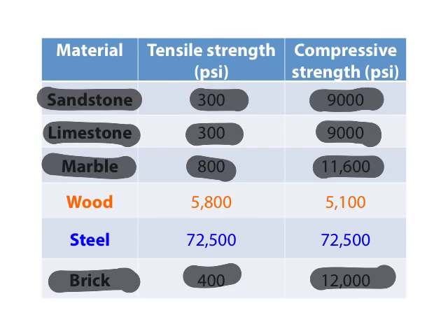So what that means is that stone is a great building material if you're using it in a situation in which it's undergoing compression. It's the perfect material for it in that sense. But you would never want to use stone when it is placed in a position where it's undergoing tension, because it will just break very, very easily.